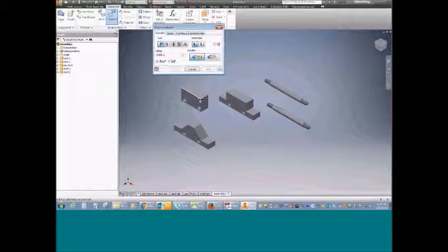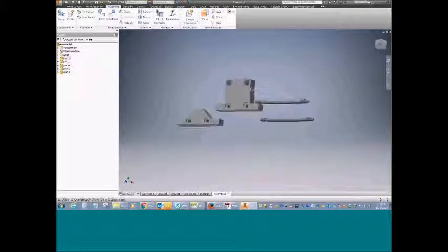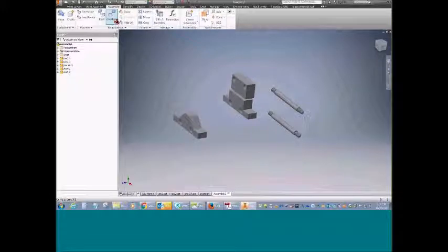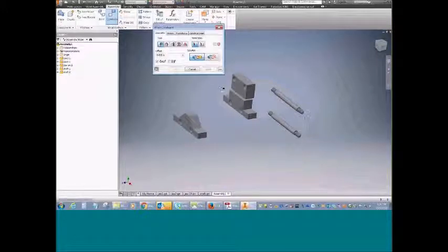And starting off, I would just have them mate these parts together, not how they actually go together, but just exploring what one flat surface to another flat surface does. And then looking at some of the different solutions, so when I pick these two flat surfaces, if I do the flush or the mate option, how that changes.